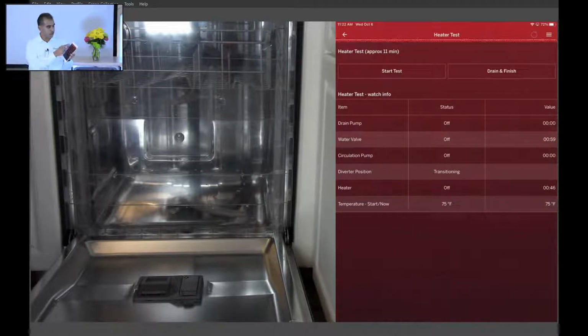And if we hit the start key, the first thing that is going to run is the drain pump, then followed by a water fill. And the reason why the drain pump runs first, and you're going to see this in all the tests we're going to show you, is because SmartHQ service is truly smart, right? It makes sure that in case you forgot to drain the water, it's going to do it for you anyway, just in the event that your mind slipped and you forgot to drain it. So let's go ahead and hit the start key and see what happens.